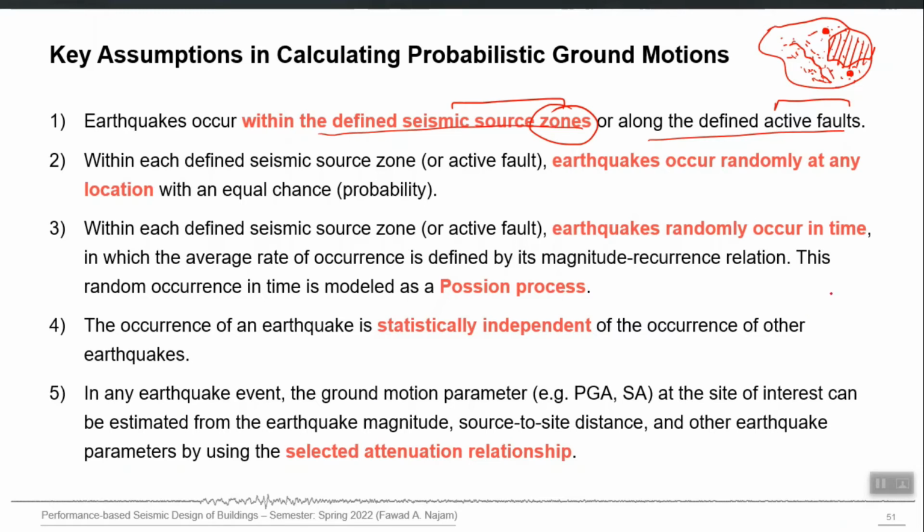What will happen if your study area is like this and most of the historical earthquakes are almost equally distributed? How will you associate them with a particular fault line? So in all such cases where you are unable to find the actual source in the form of a particular fault, you make area sources.